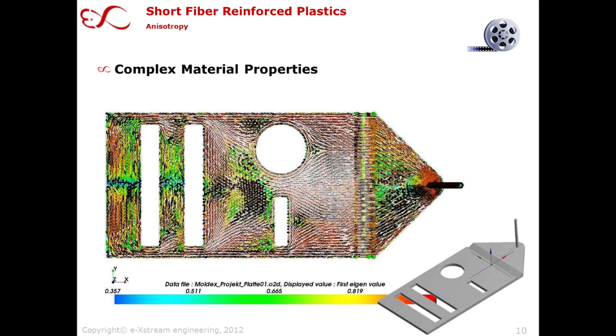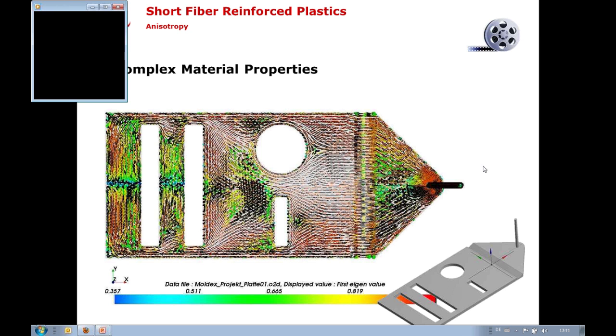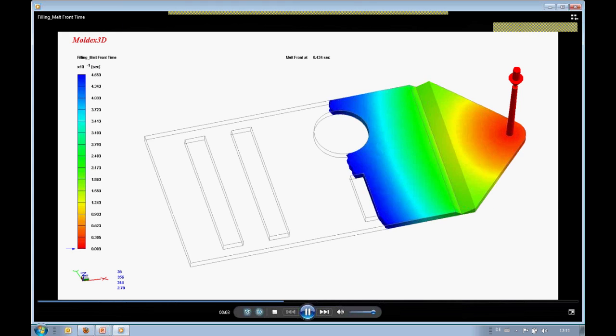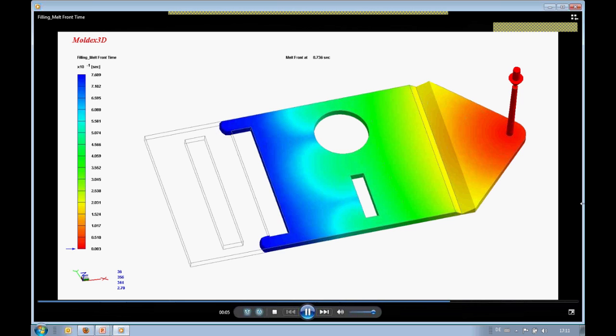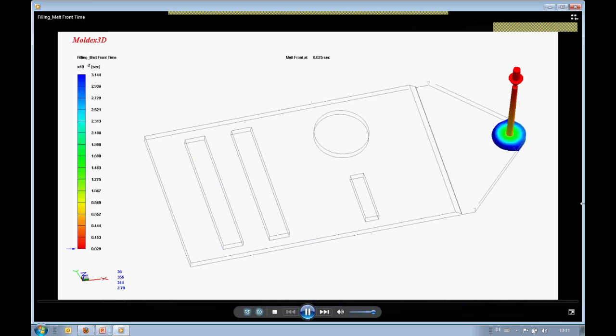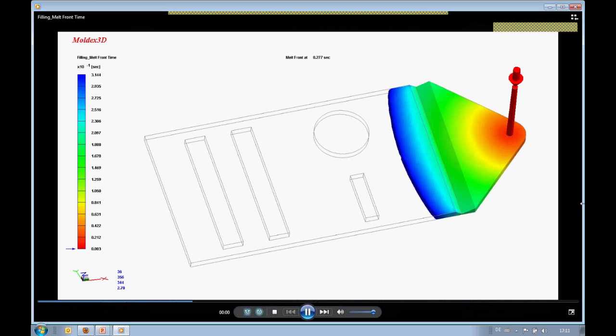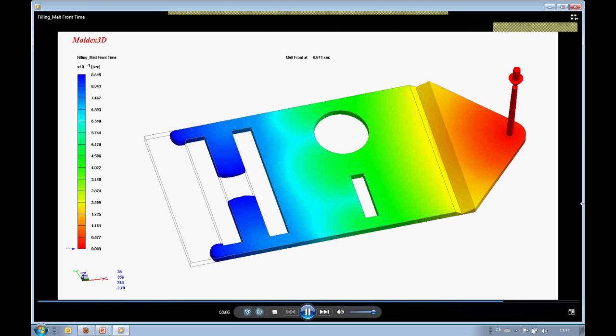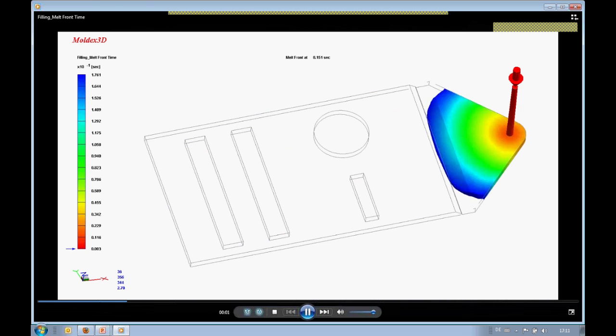And now you can think about the consequence on the level of the part, and here we have some artificial test plate that we created for reducing this discussion to 2 dimensions. And I'd like you to take a look at the movie here of the filling. So here we go. You'll see that we come in with a mold front. The mold front hits some barriers. And basically what we create in this scenario is that we induce flow lines first and then static weld lines in different local areas of this plate.